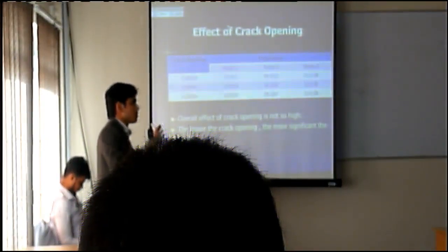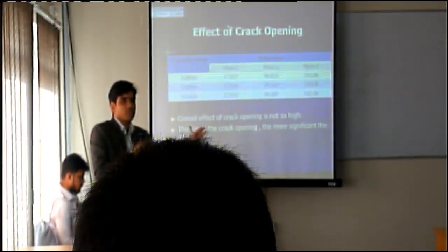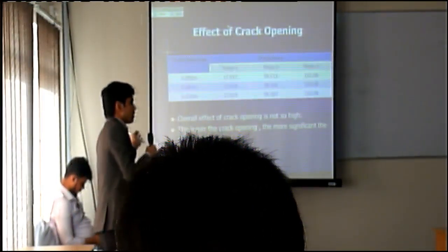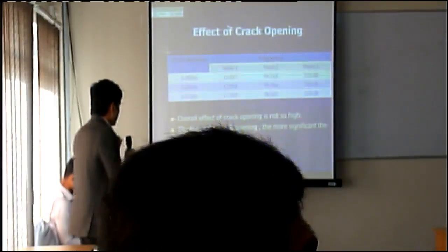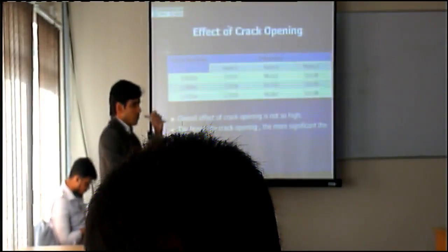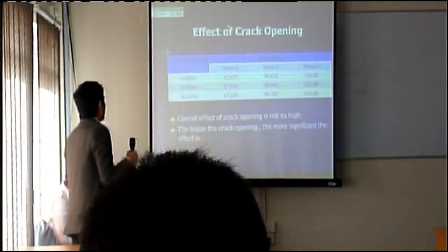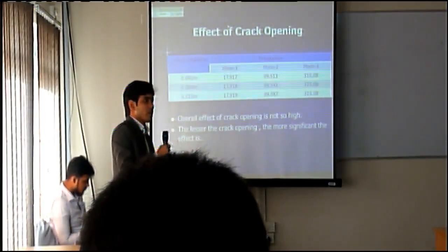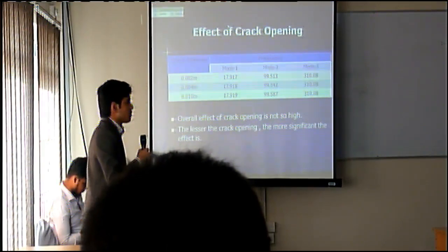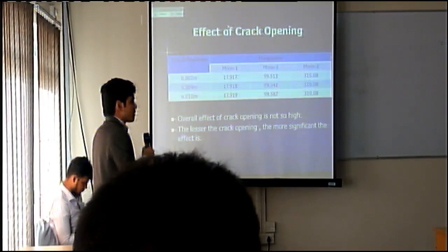and that's why I think the crack opening size is omitted in those resources. If we take 10 millimeter or 20 millimeter or 15 millimeter, that result will not vary in the first digit, but it will be significant when we take the crack size very small, 1 millimeter or 0.5 millimeter, but our limitation is that the 0.5 millimeter crack we cannot simulate using the available Abaqus software. So I have taken 2 millimeter as the crack opening size.